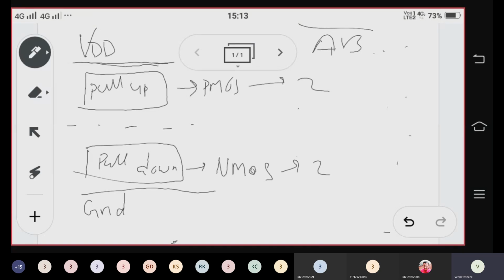The two inputs are in a product in our output equation. Product means we have to connect NMOS transistors in series. Whenever a product is there, we connect NMOS transistors in series, and PMOS transistors are connected exactly in the inverse of the NMOS transistors. Here NMOS transistors are connected in series, which means PMOS transistors should be connected in parallel.